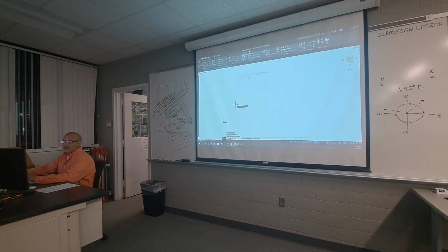Alright, so I'm in my polyline command. I'm going to move my cursor down here to the bottom right because I have no need for it. Everything's going to be keyboard entry. I'll see people start drawing and they're rolling their mouse wheel back. "Mr. P, it won't let me zoom out. I have to hit escape, zoom extents." No, you don't. Wait till you finish drawing it before you zoom extents. Don't worry about trying to see that last point you picked. Trust your tool. If nothing else, look at your command line before you hit enter and make sure you type the right thing in. Other than that, you do not need to see all of these corners.